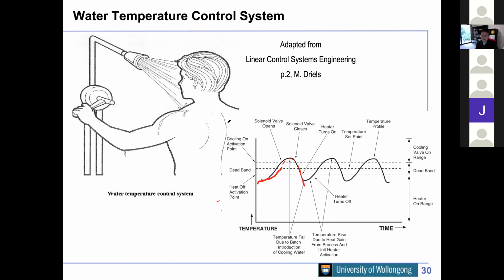So normally I will turn the heat off if the temperature is too high, then turn the heat on if the temperature is too low. But we create a kind of threshold. Say this is 40 degrees, and up and down a few degrees is a comfortable zone for me. Then you just have an electrical switch over there, controlling the temperature by turning it on and off.